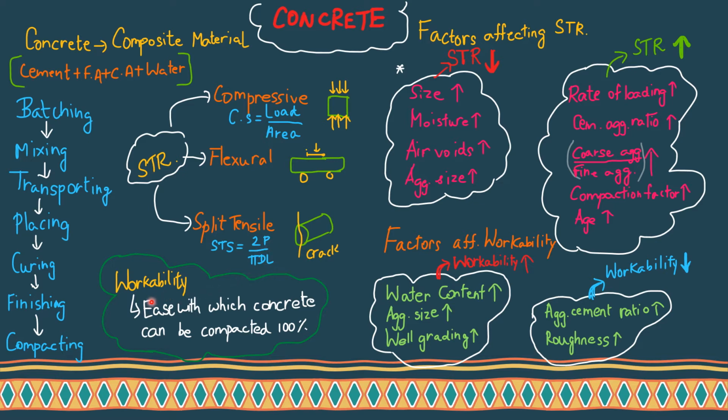Next, the term which we are going to see is workability. Workability is the ease with which concrete can be compacted to 100%. The concrete should be easy to work. You have to easily carry it and place it, or easily transport and place it. That is workability.